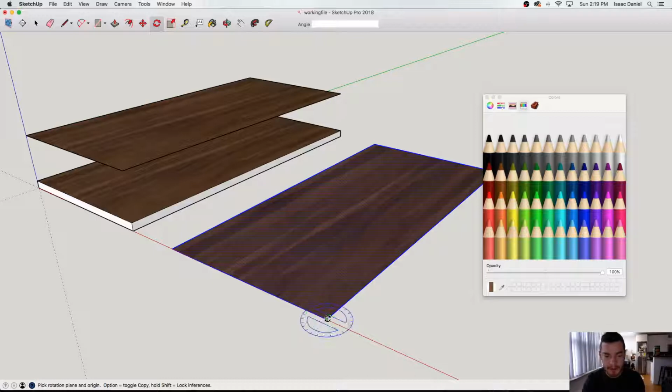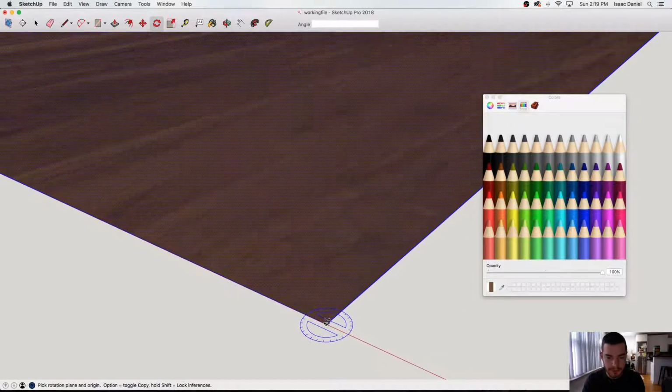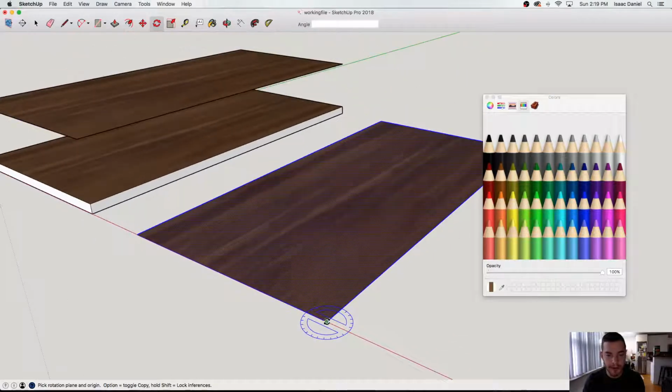And you can rotate this panel in a lot of different directions. You can go around the panel to find how you want to rotate it, or just find a corner that SketchUp will snap to. If you're unsure, you can zoom in, but it should snap right away. And it brings up a bunch of different compasses or protractors. So we want to make sure that we're going to be orienting along the green axis. So SketchUp will show you that, and then you can just rotate it.